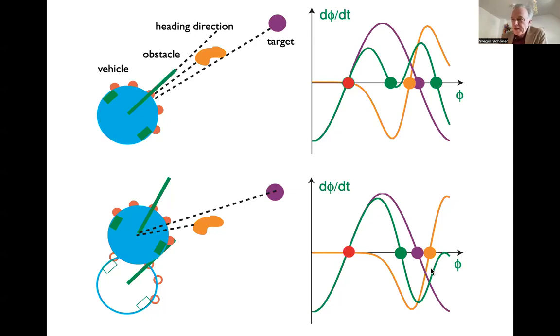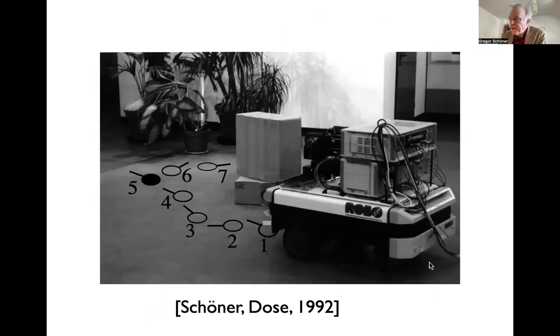So we did back then a real vehicle implementation. It is ancient work. This was the state-of-the-art robotic platforms, about 1 meter by 1 meter, and we used a very fancy way of the cameras here. We used some visual approach that was able to detect these obstacles because they stick out from the surface. So by doing some stereo method, a very low level approach, you get some information about anything that's not in the surface. And therefore it was, for instance, here able to detect this obstacle and then move around the obstacle.